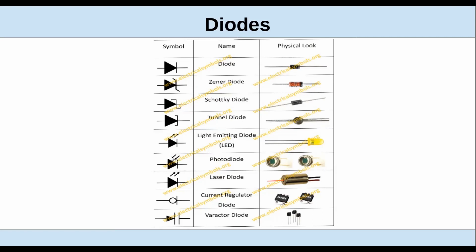So we have the light going into it, and they have a little window in the case so that light can get to the semiconductor wafer. It actually turns out that all the devices are photosensitive. They discovered that, and they can enhance these so they're more sensitive. But if you put a regular diode in a clear case, it would be affected by light.